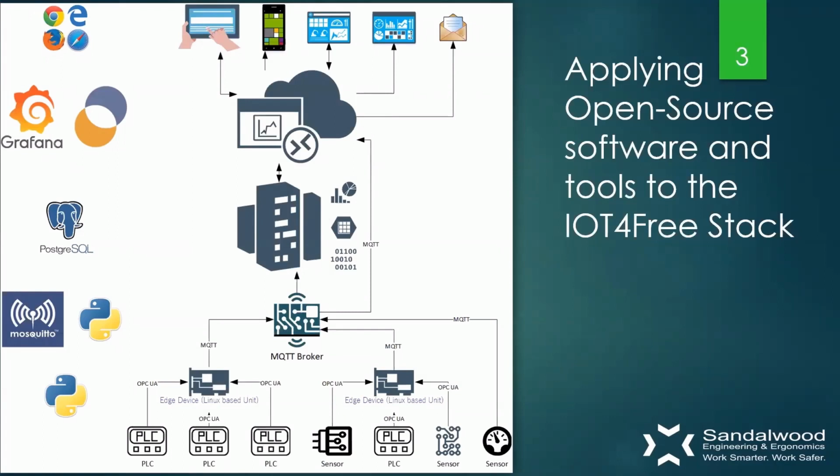But the overall structure of the stack is based off of the general tech stack as we have outlined here. Below, at the bottom in this lower section, we are using OPC UA and MQTT messaging protocols, which push the data from our source devices to an MQTT broker. This broker allows agents on the PostgreSQL server, in our example, to subscribe to them, allowing for their consumption to open source databases. This broker also allows for Grafana, which is what we're using to visualize our data, to subscribe to the same topic for real-time data presentation.